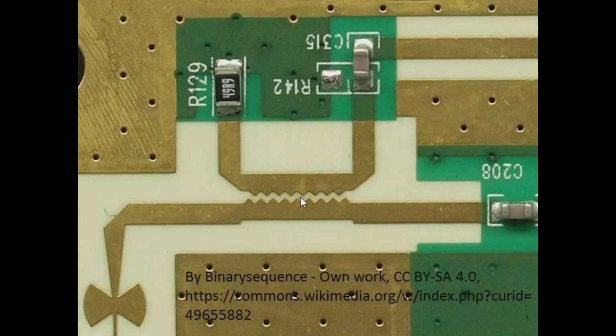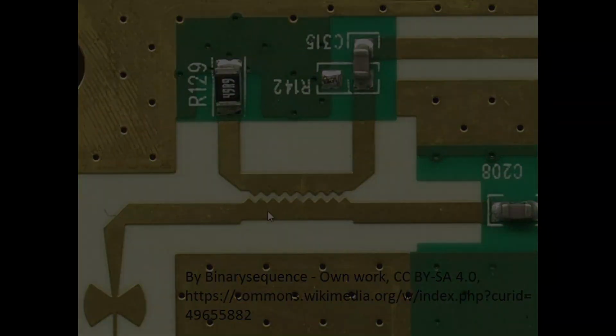The only problem with it is trying to design this is no longer straightforward. So how do you make one of these? Well, unfortunately, it's largely an exercise in cutting and trying. I think what I would do, and I hasten to point out that I've never done this before, is that I would try to make the length of this path such that the total phase delay for the even mode and for the odd mode through this coupler are the same. And the gap is correct for the coupling. That will not be exact, probably not by a long shot, but it's a place to start. And then you can rev up your trusty EM simulator and fine tune it.